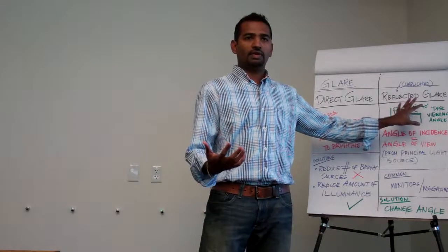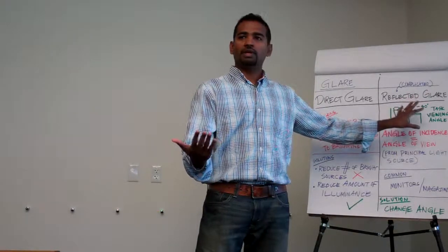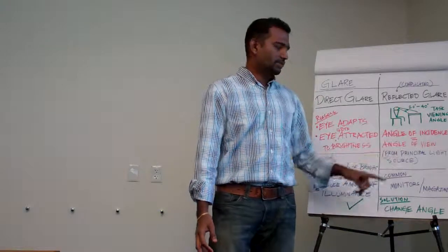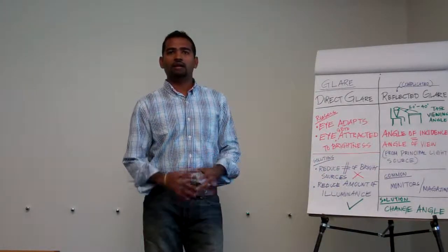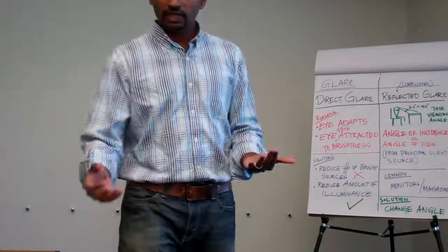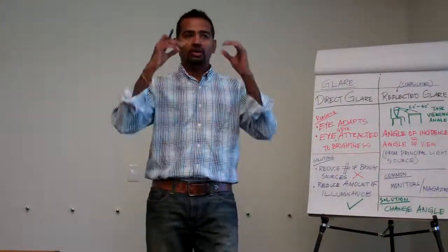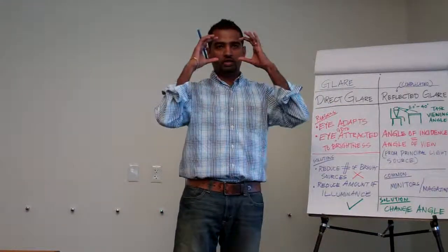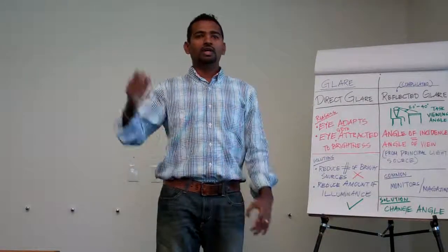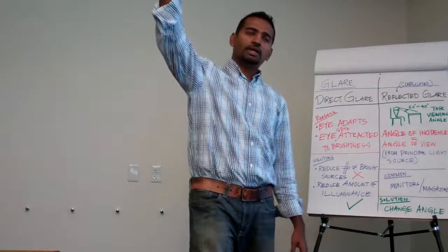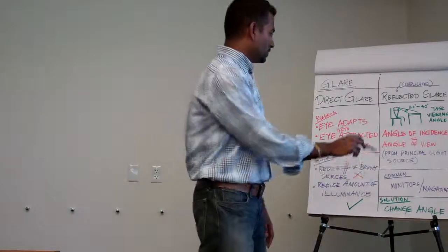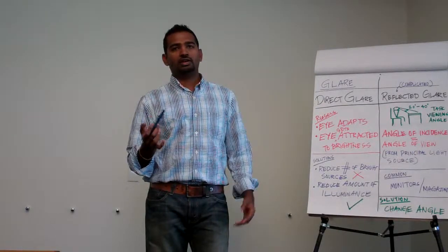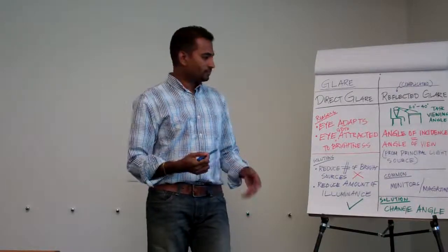There's the veiling reflection that we get off of a magazine when we read it, and the phenomenon is because of the angle of incidence being equal to the angle of view. In a normal task like reading in a classroom or an office, our normal angle of view is between 20 and 40 degrees. So if your light fixture emits light in this 20 to 40 range too, we're in trouble. That's why most downlights are not always good for veiling reflection issues.